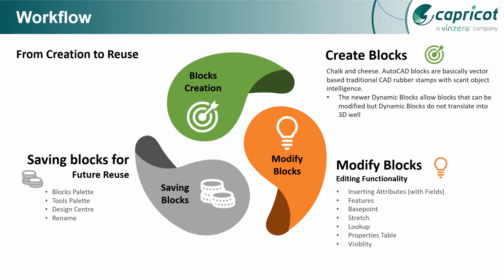So you need to understand that those blocks are going to be saved into your palette. It can be stored in a different drawing, it can be saved into a tool palette, or it can be stored inside the Design Center, right? And when you work on the next project, you can rename them according to the features.